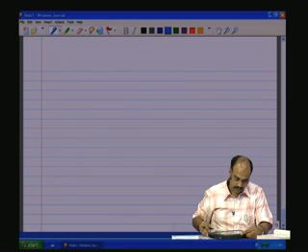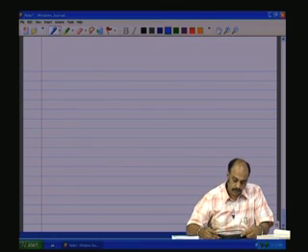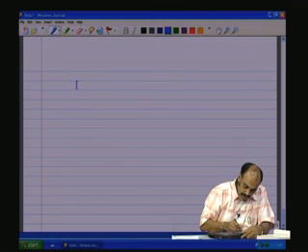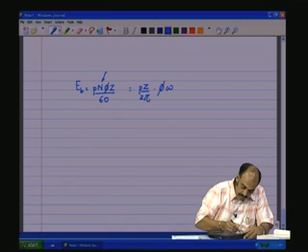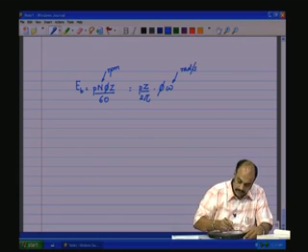Now, if we take this equation Eb, which is equal to P n phi Z by 60, or P Z by 2 pi into phi omega, where this is in RPM, this is in radians per second, and this is K which we had defined. So, which is equal to K phi omega.